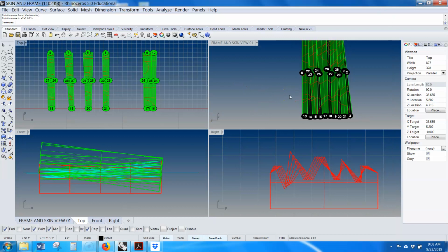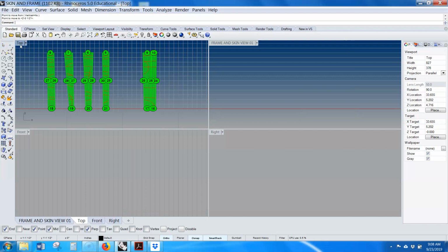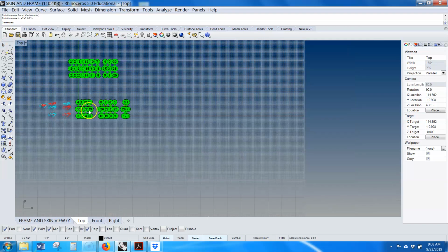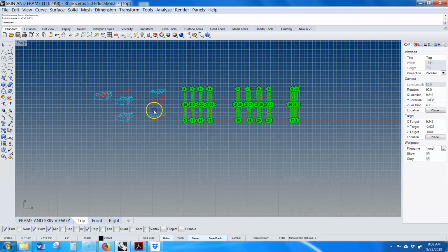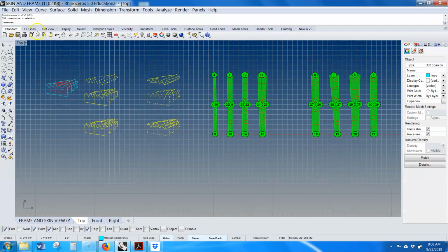So when you go and print it, do you put it into AutoCAD and print from there? Yes, guys, time out. Don't pack up yet. Always print from AutoCAD. Don't print from Rhino. So bring it in. So how would I print this? Still recording here. So what I want to do is take these drawings, go File, Export Selected.